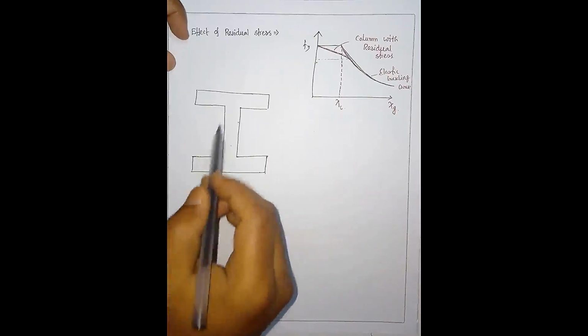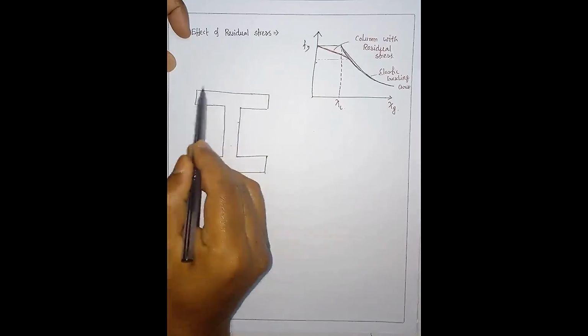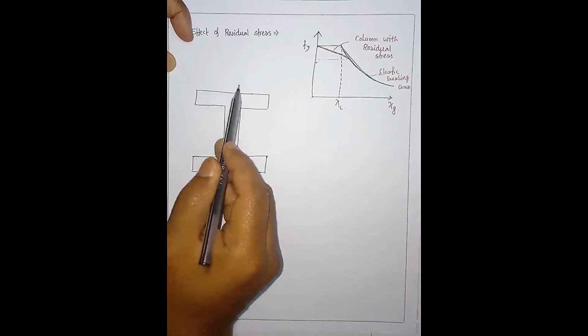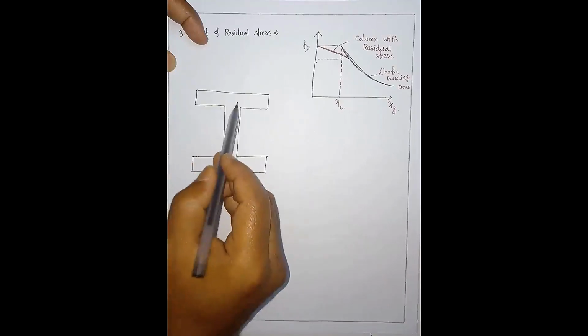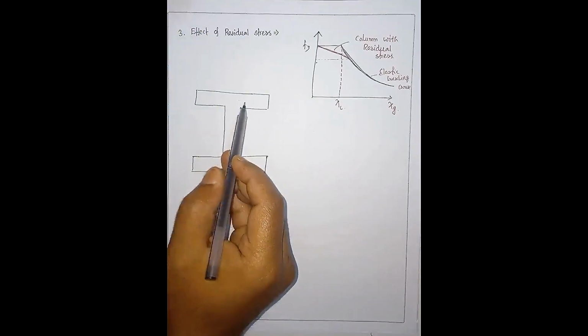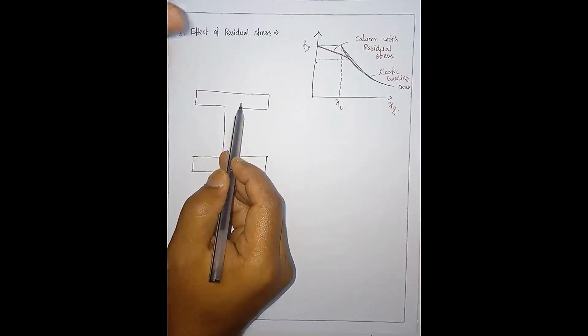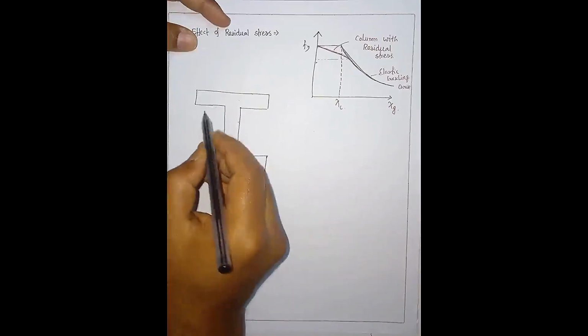So what I'm saying is, these exterior faces will cool down at the very beginning, but the interior part will not cool down at that rate. So there will be some temperature difference, or stress difference actually. That's why some stress will exist here.